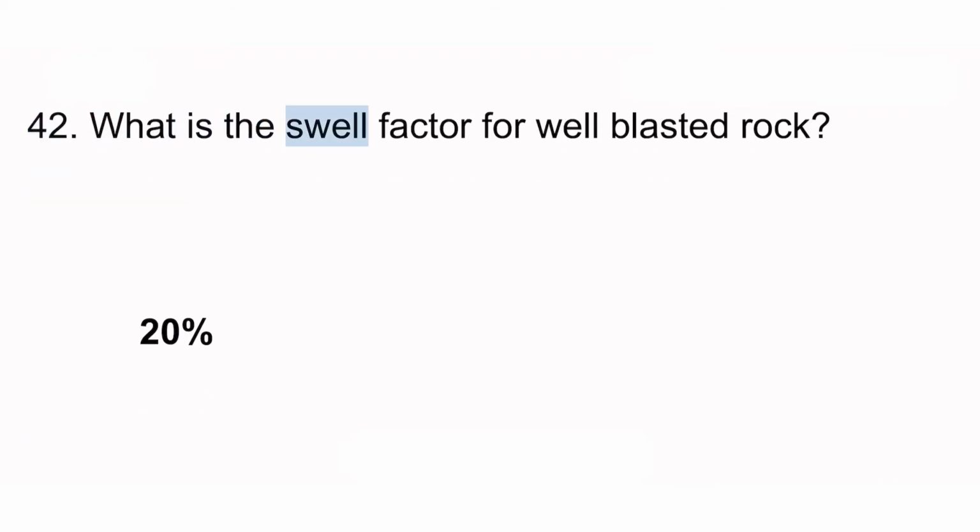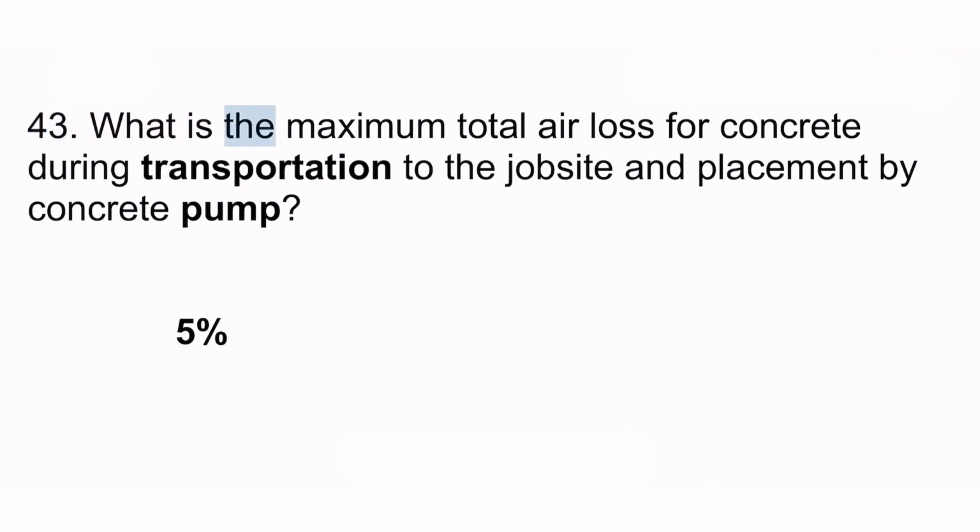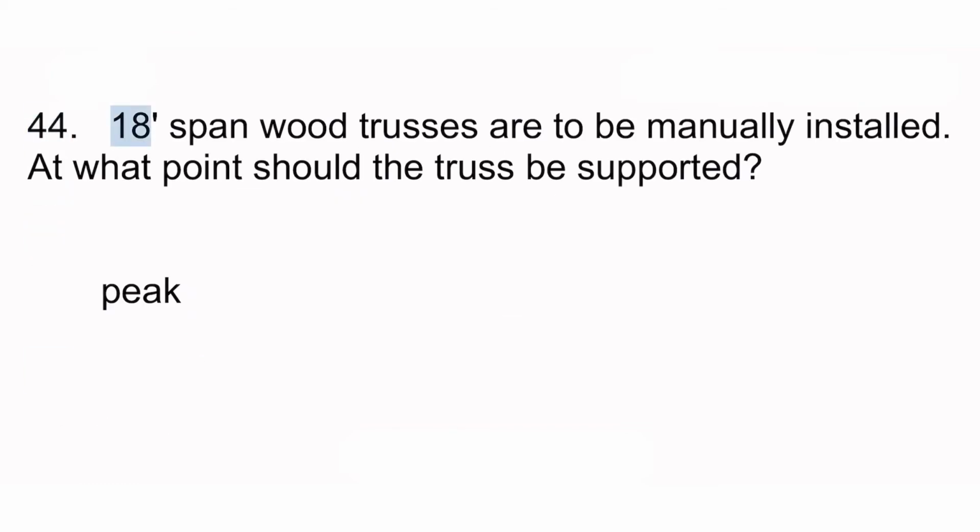42. What is the swell factor for well-blasted rock? 20%. 43. What is the maximum total air loss for concrete during transportation to the job site and placement by concrete pump? 5%. 44. 18-span wood trusses are to be manually installed. At what point should the truss be supported? Peak.